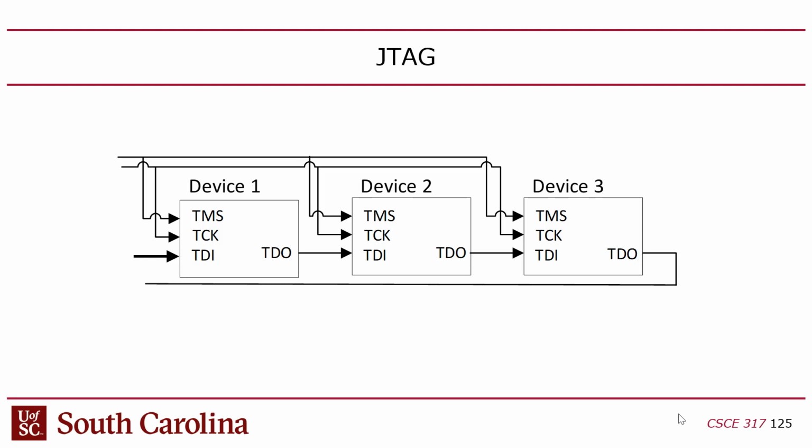So each LUT is 7 bits and there's 115,000. So just to program the logic gates on the FPGA, I'm going to have to send 115,000 times 7. But there's other configuration bits on the FPGA as well, like all the memories, MUX settings, routing fabric setup, right?